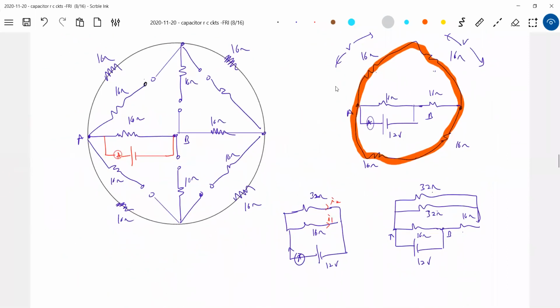Okay, can you work out here? So I'll just leave it. So how to calculate this drop? Okay, again, you have to come back from here. 32, this will be 16 ohm. That 16 ohm, I think this will be 6 volt. The drop across this will be 6 volt and the remaining... anybody, can you tell me the drop V, because the problem will get over. Or we can find the net resistance and then find it. Don't do all this, very lengthy.